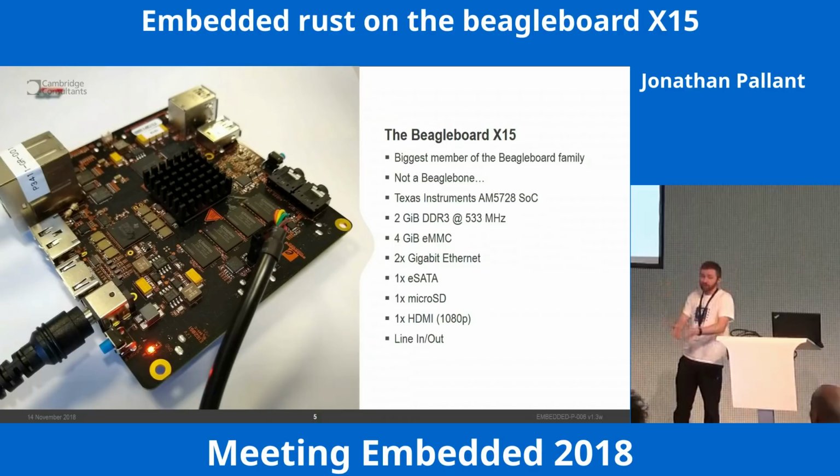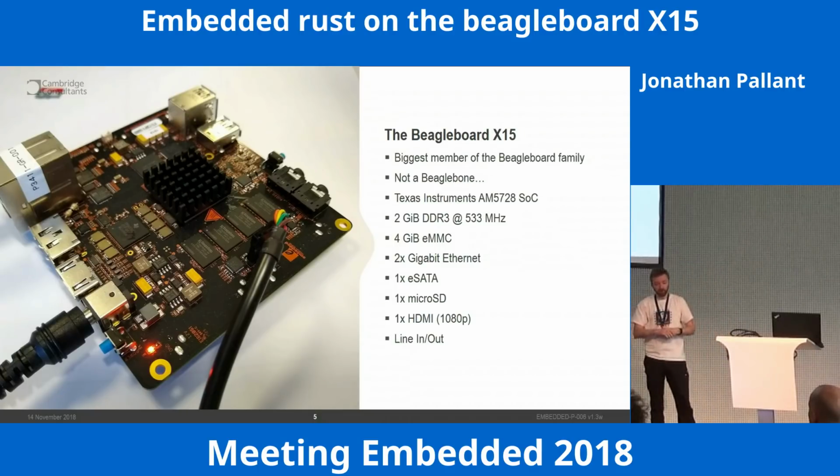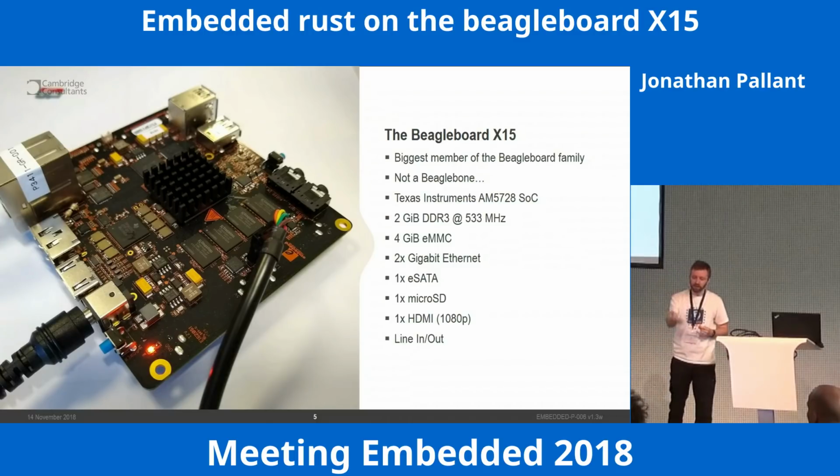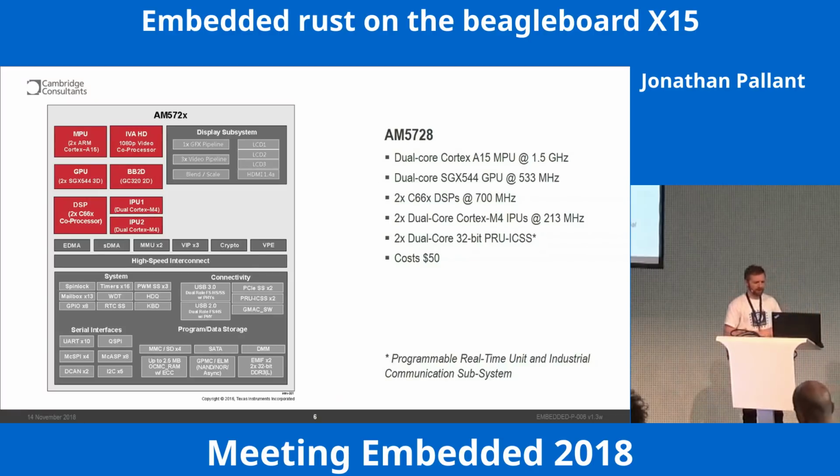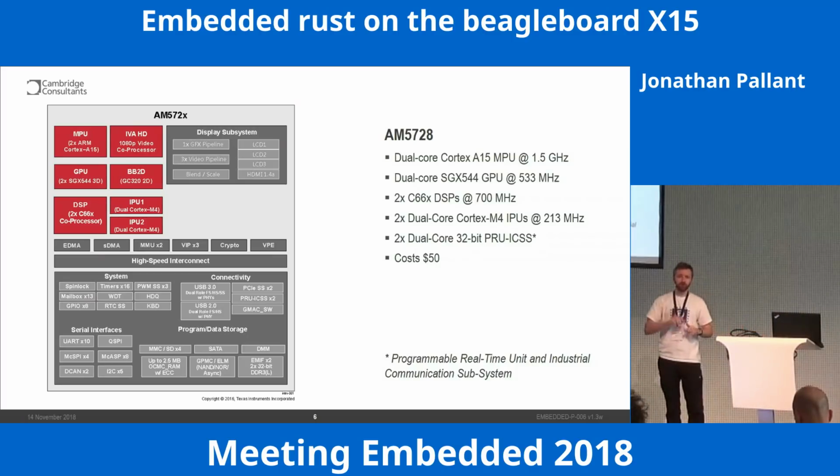You can make an argument this is not an embedded system, this is a computer. And yes, if you fire it up on your desk and run Chrome on it, it's a computer. I think it depends what you're doing with it. You can definitely do embedded applications on a board like this, as we'll see. So what does this look like inside? Well, there's a lot going on in here. We've got 2 Cortex A15s, so it is a dual processor, dual core computer.